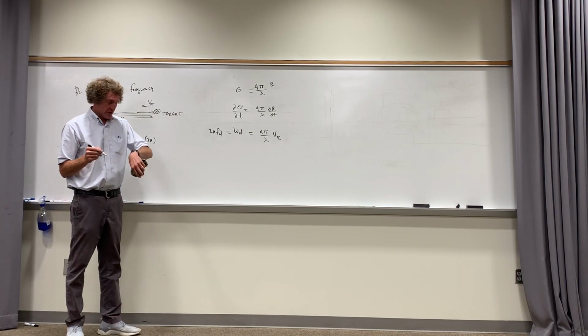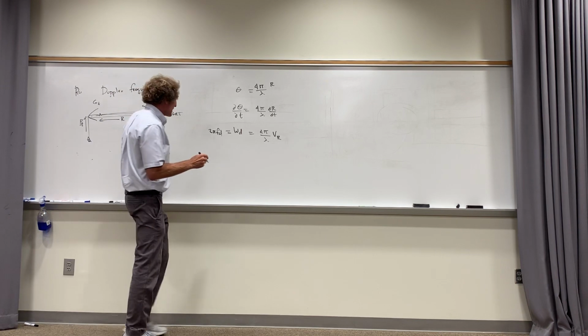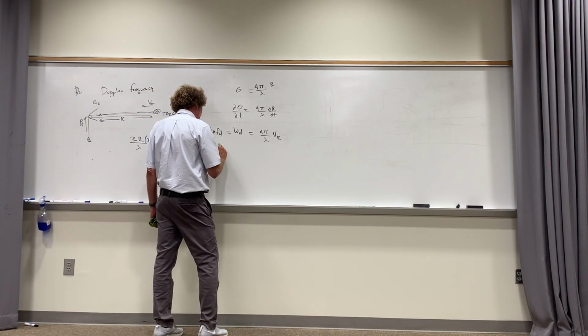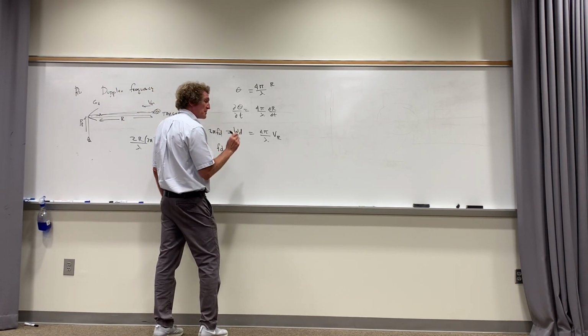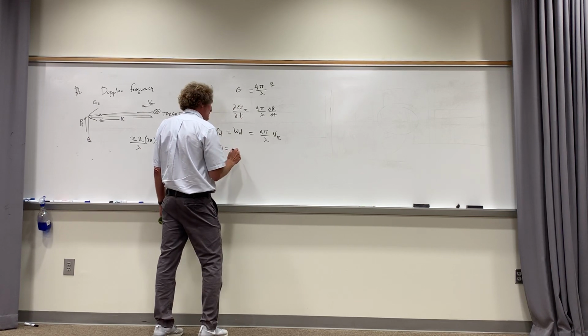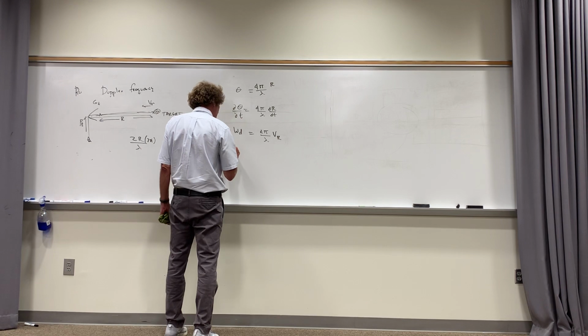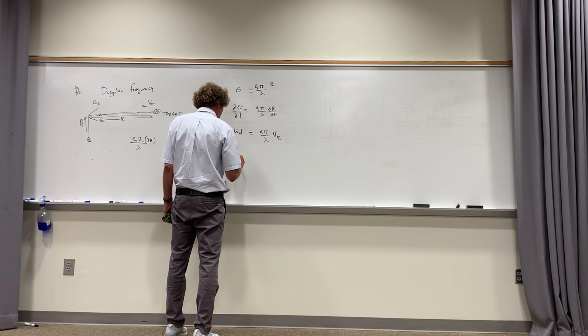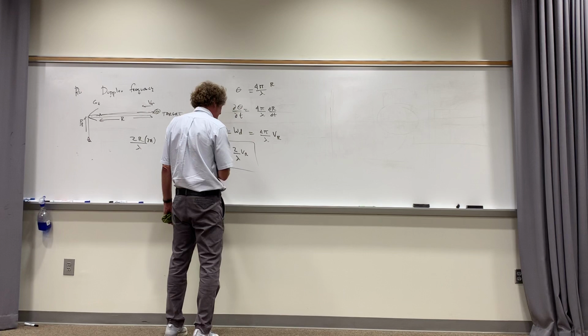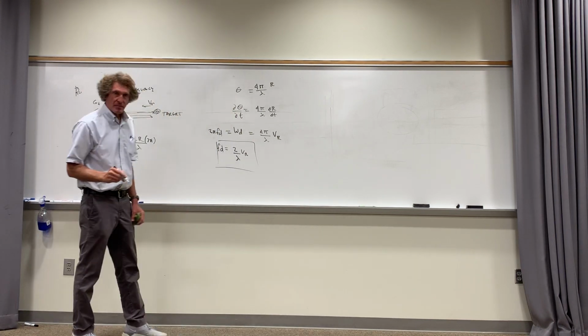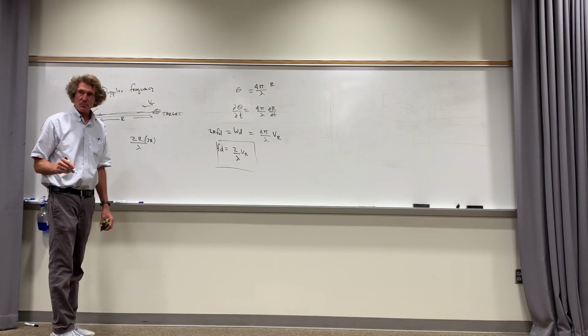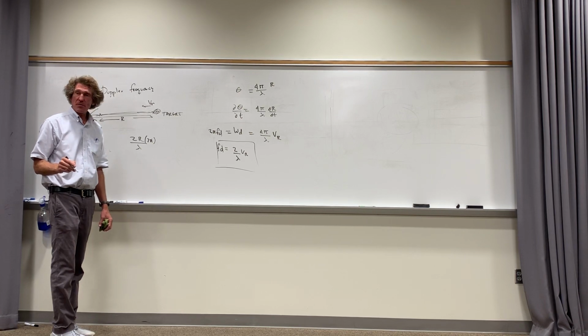And then what that also means is that f Doppler, or the Doppler shift for non-relativistic movement, would be simply, well, that's 2 pi, 4 pi, I get 2 over lambda times V_R, and that's the Doppler shift right there. Now lambda is the free space wavelength. I'm going to put it in terms of something else in one second. Y'all follow me on this?